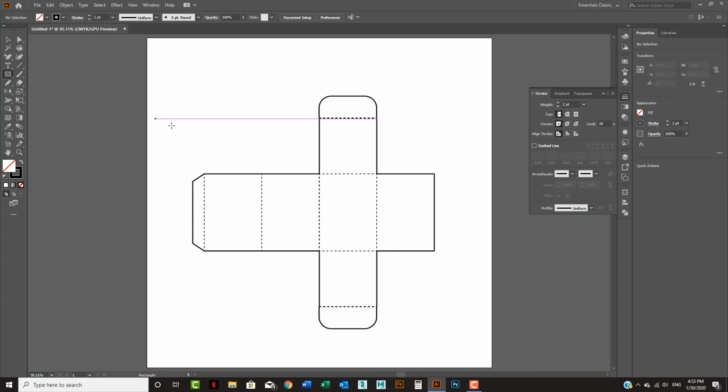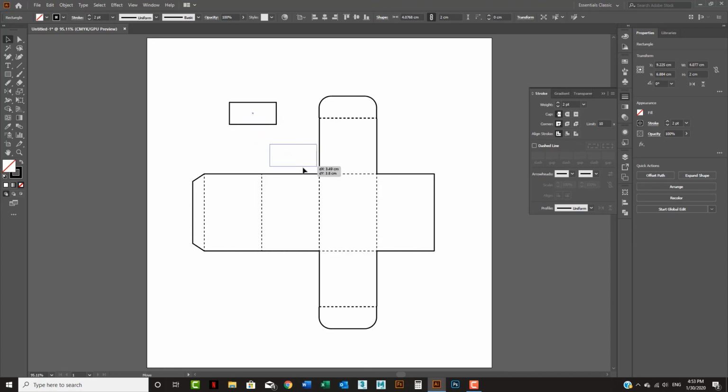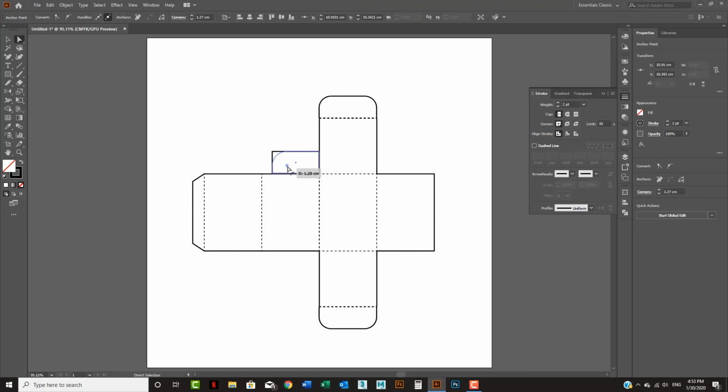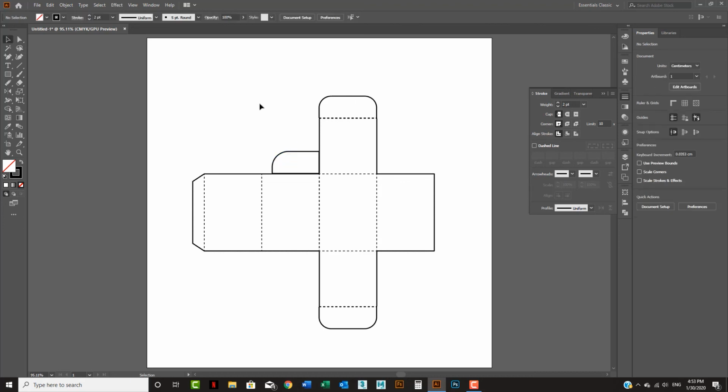Again, for the dust tab, I'm going to use this box in here. So let's have it, for example, half of this. This one is 5 centimeters. I'm going to stay with 2.5. So click in here. Width must be this one. Height, I'm going to give it 2, which is okay actually. I'm going to stay with the 2. And I can move it a little bit in, something like that. And let's leave this one here. Then I'm only going to select this one and give it a kind of rotate like this.